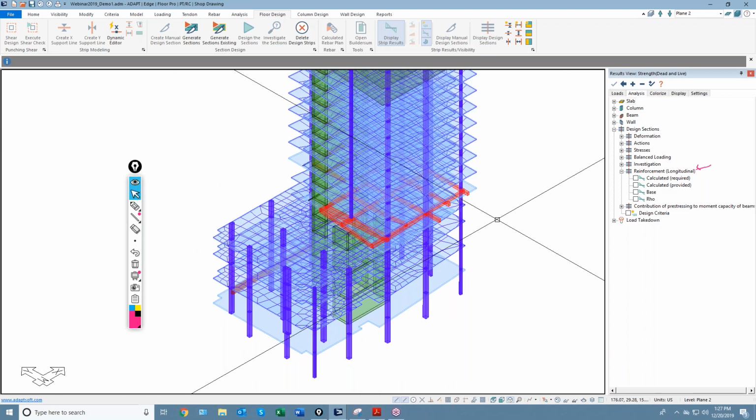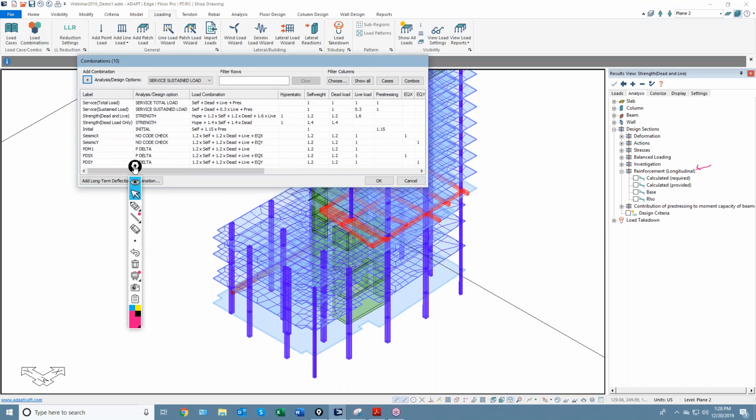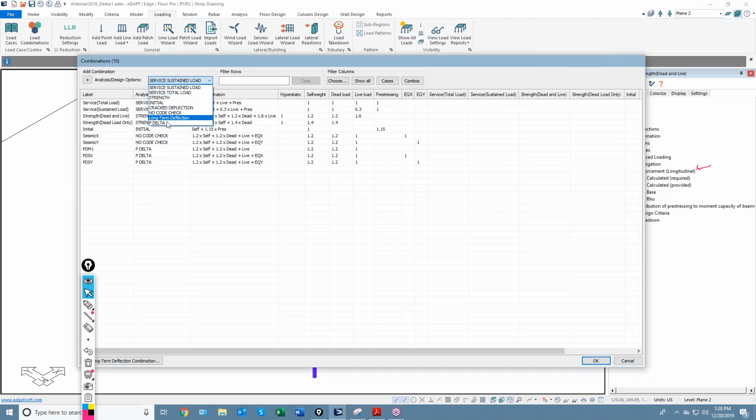We're going to first talk about P-delta. So the program now considers second order analysis, big P-delta, I'll say, and we do not use the iterative method. We use a non-iterative approach where we calculate a geometric matrix and use that for the solution. If we go to load combinations, you'll note that there's now a new option here, which is called P-delta.